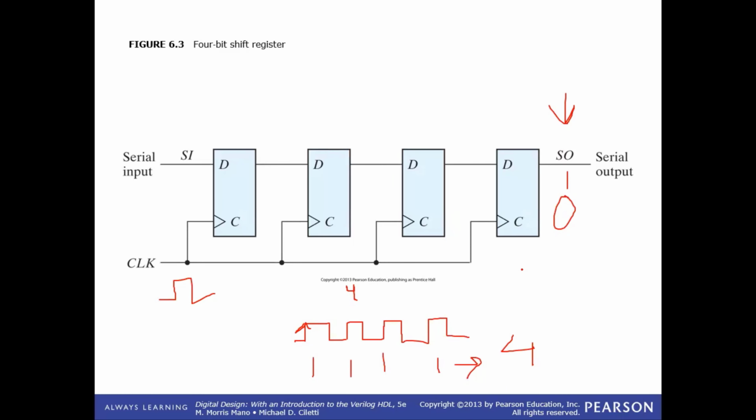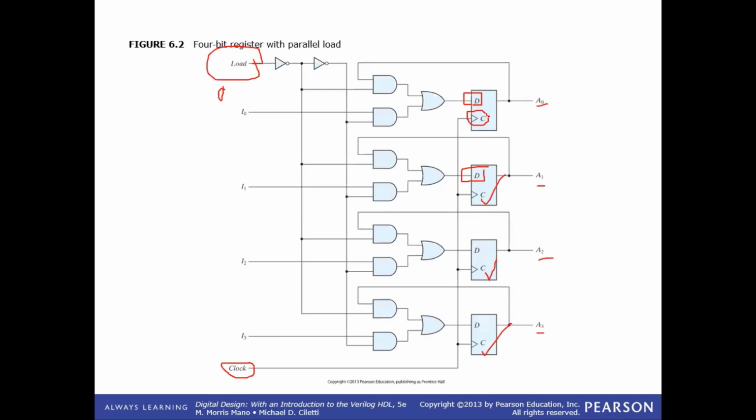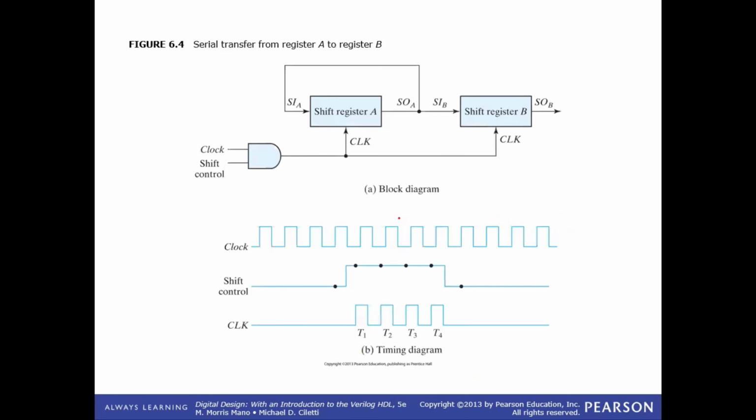Whereas the positive thing, the profit that we have while implementing these circuits is that the circuitry needed for these circuits is inexpensive. It's quite a lot cheaper because we would be needing 1,000 D flip-flops for 1,000-bit data to be transferred to the output over here. Whereas in this case, we do not need 1,000 D flip-flops to reach the output. You can have even a single D flip-flop or two D flip-flops, and you just need to transfer the input to the output turn by turn. The only thing that's needed more over here is the number of positive edges of the clock.